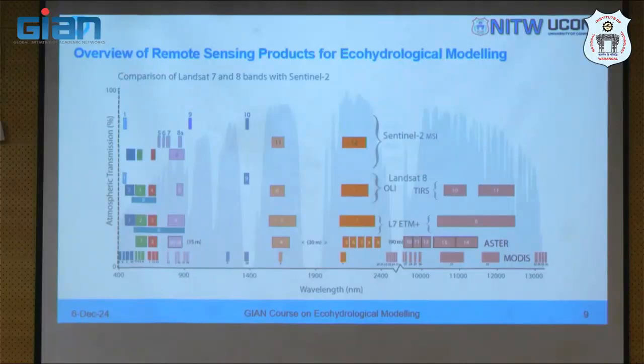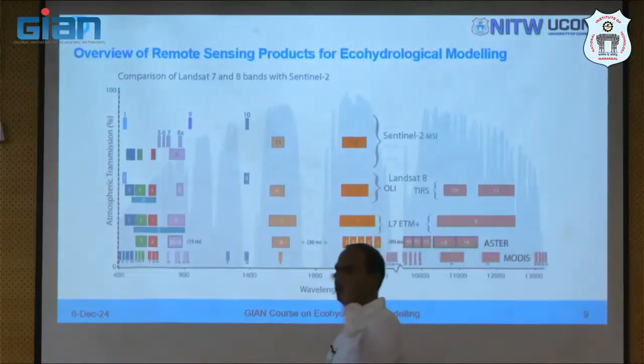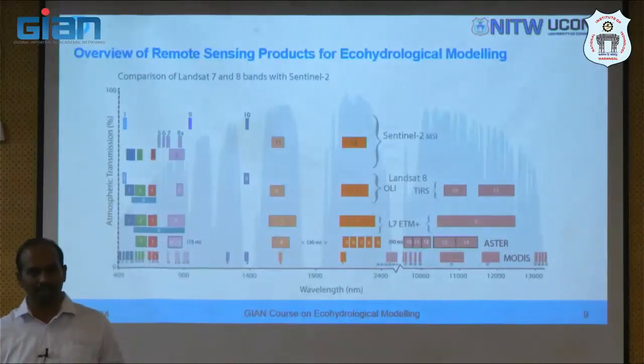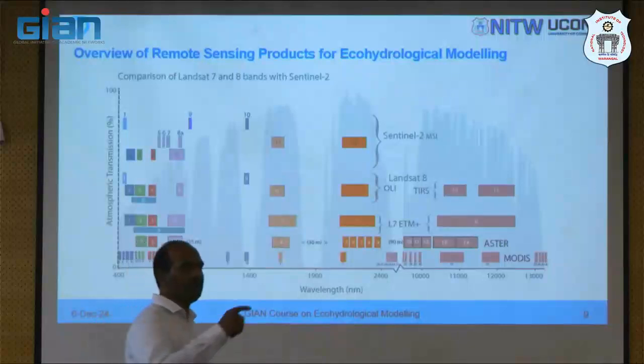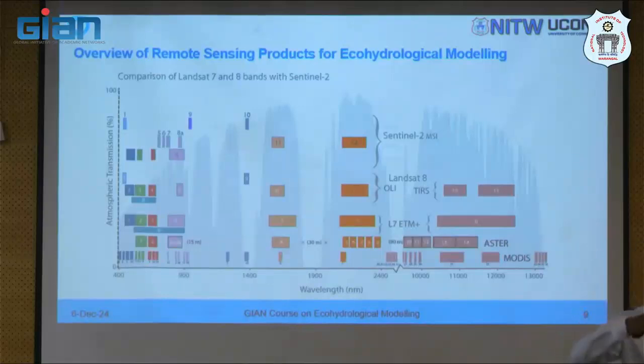You need to have ground truth data, and then based on that, you need to identify a spectral signature. Now that spectral signature can be across different bands, or within a band, a time series, right? If it is a concrete surface, you expect across time it should be more or less the same. The reflectance values should be more or less the same, right? But with crop growth, across time it is going to vary, similar to a forest. There may be some variations in some of the reflectance values.